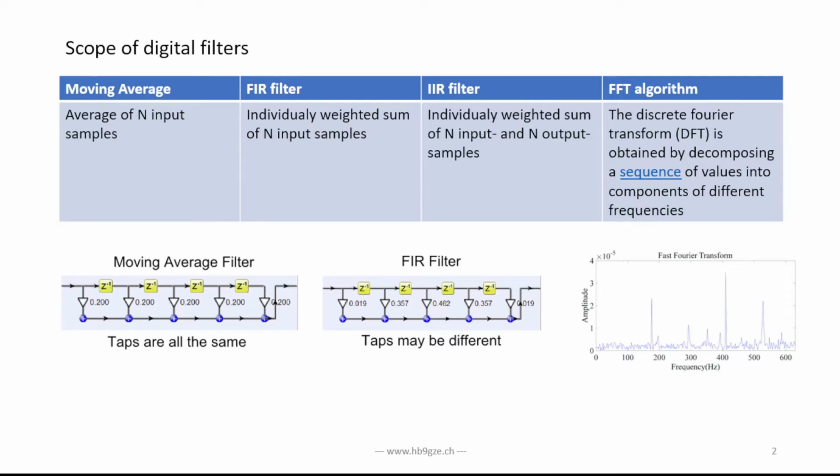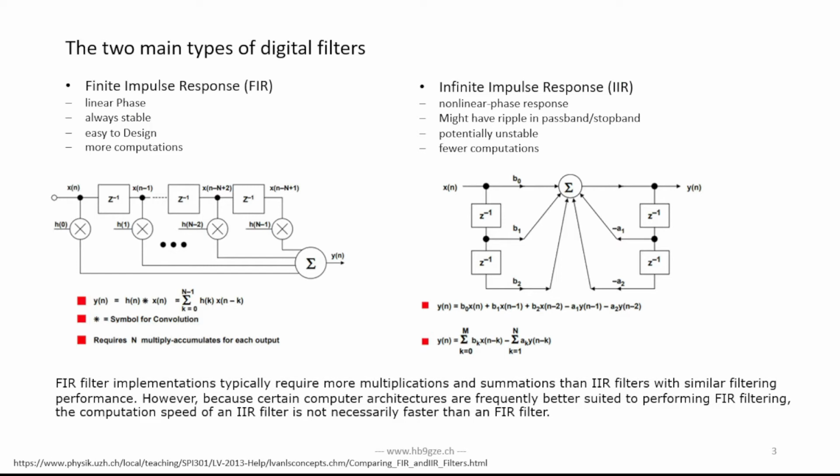And then, of course, fast Fourier transformation. That's a method, an algorithm, for how to do discrete Fourier transformation on sampled data, like we have here. We take the same sampled data and we do DFT on it, and then we get as output the frequency components that are in this signal and at what amplitude they are represented in this signal. So it's somewhat related to digital filters.